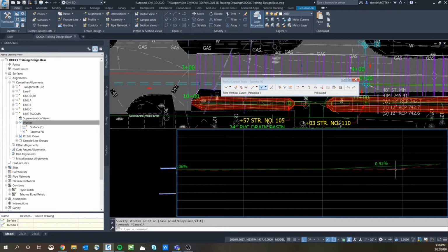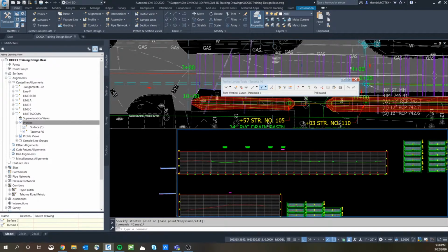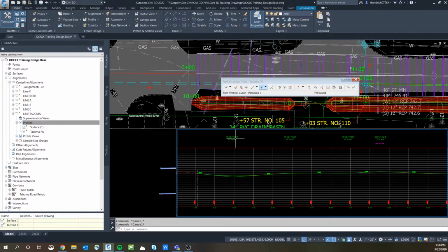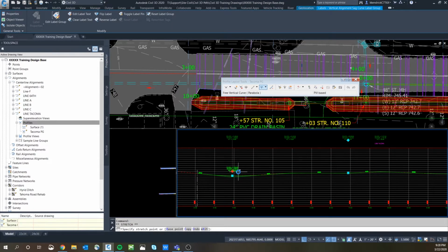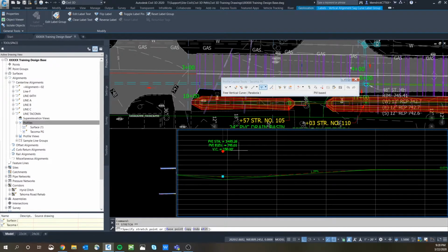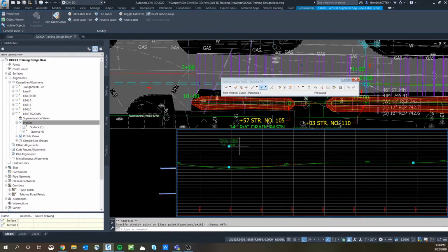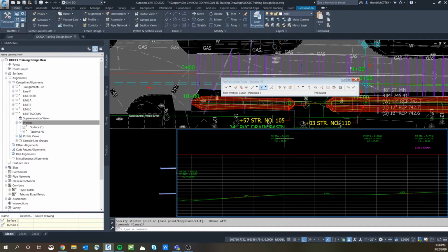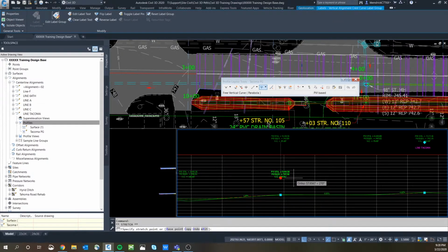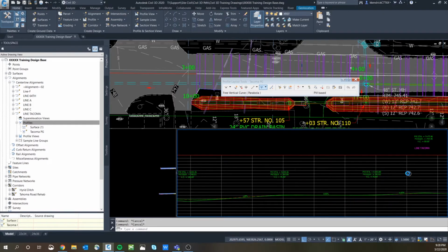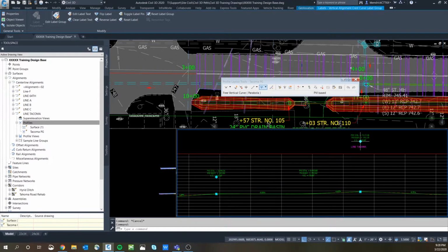Alright, I think that's enough playing with the curves. Once you have all those in, as you can see, because I did the full label, it does label the crest and sag curves. Pull those down where you can see them. Ideally, you're going to want those PBIs to be at even stations, your elevations to be as good as you can towards something even.